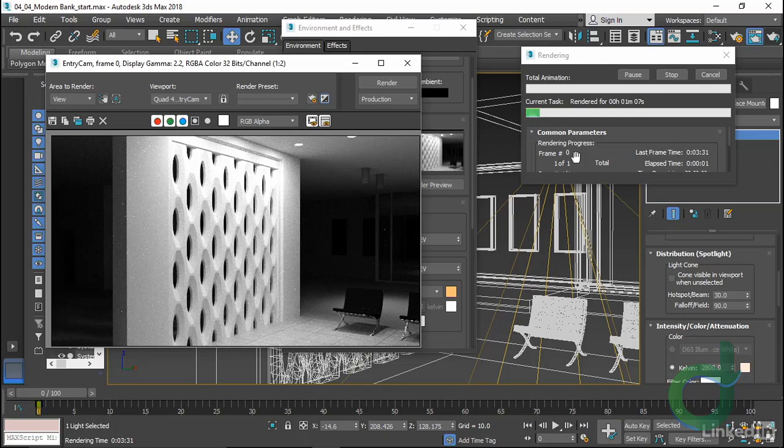Now, what I am looking at in this is, running in black and white with that exposure, do I have anything in here that needs adjustment in normal or in shine or any other property besides the color of the material? I want to make sure that without color confusing things, the way the light is looking on the objects is correct. It definitely looks like my surface mount cans need some attention.